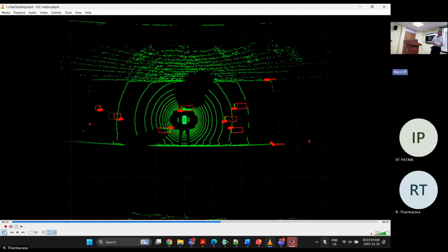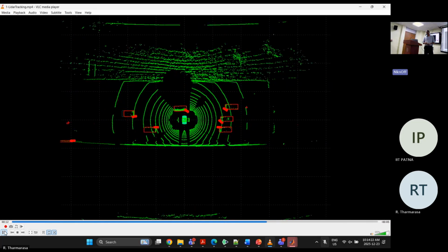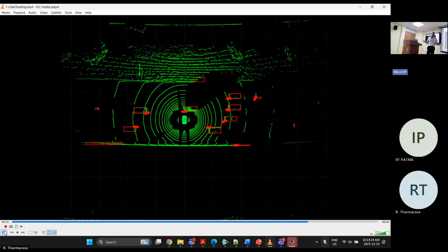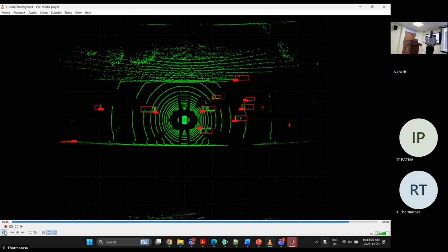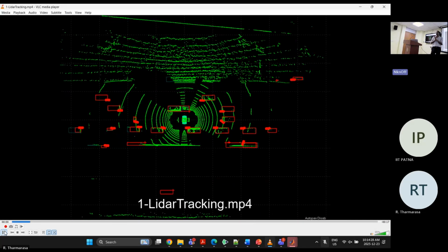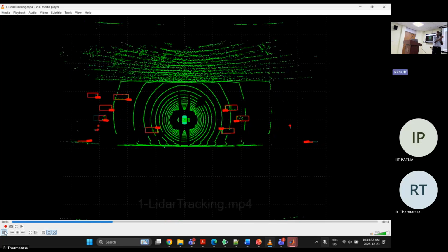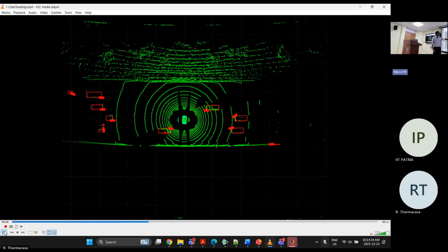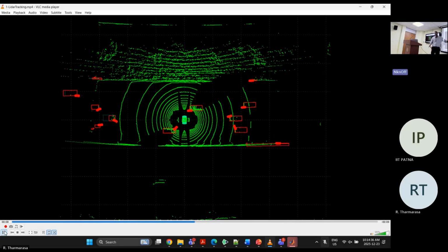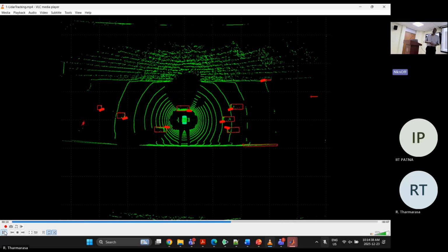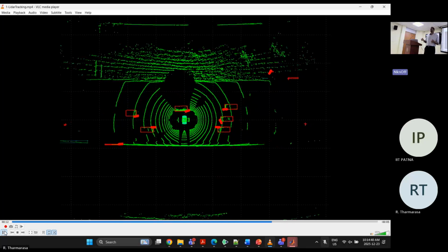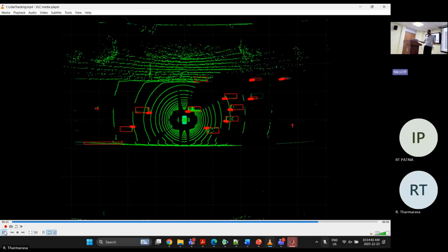If you think about a self-driving car, we want to track the vehicles around us before we make any decision. Okay. So in this case, our detections are the LiDAR returns, and the red ones are the tracks that we produce. Then the tracks will go into the high-level decision making, where you want to decide whether you want to brake or not. Right?